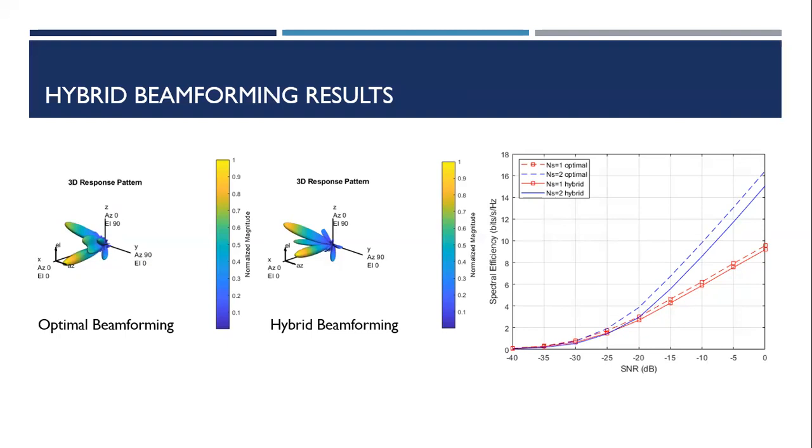analog beamforming is that we are only able to achieve one particular beam using one single antenna. Comparing that to digital beamforming, we use different waves which are fed into different antenna elements, and different main lobes can be produced by digital beamforming. But the drawback here is the usage of more advanced hardware, because now we are not using the same wave as we were using in the analog case. So for digital beamforming, complex hardware circuitry is required.